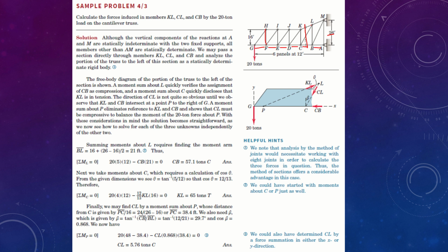If we start with the method of joints, you can start from point G. Then from point G you can go to point H, then from H, F, I, and so on and so forth, and it is going to take a lot of time. One of the simplest approaches is using the method of sections, and we need to identify a certain point where we can eliminate the maximum number of forces. So we know the forces acting on this particular joint will be along KL,